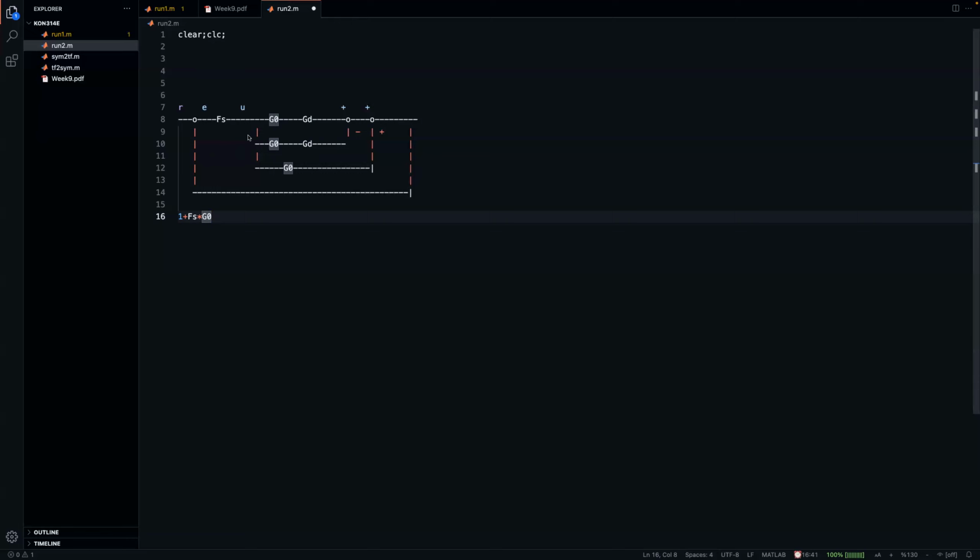We're preventing that from entering the denominator of the closed loop. So that's quite important. And this is a special structure for systems with delays, which is called Smith predictor. And it is used to get rid of this delay in the loop transfer function. Therefore, we have a proper characteristic polynomial.